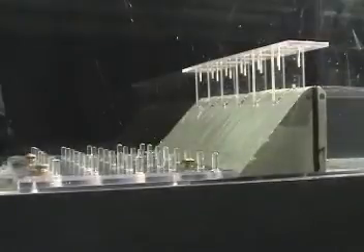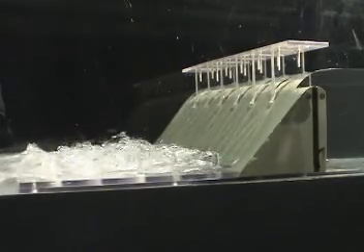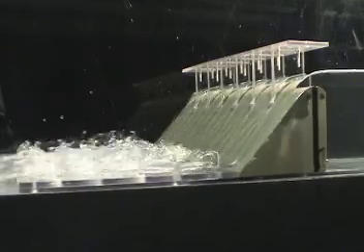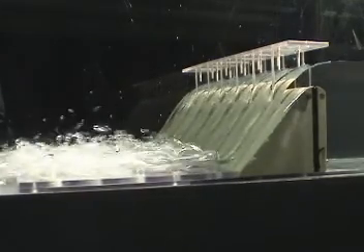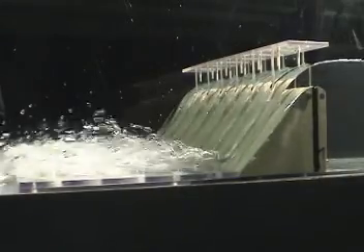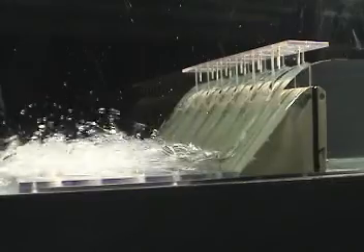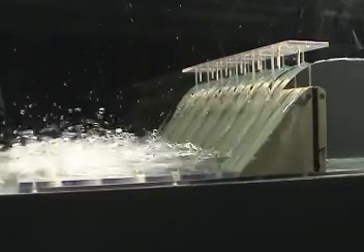In this experiment in a water channel, or flume, the fast-moving supercritical flow downstream of the spillway causes erosion of the riverbed. In this flow, the Froude number is the most important dimensionless parameter to match between the model and the full-scale spillway. The Reynolds numbers don't match, but it doesn't matter.